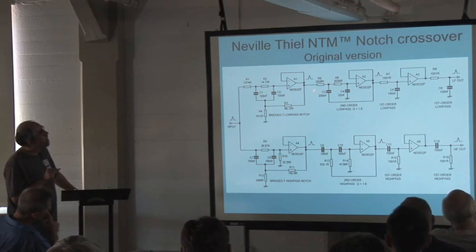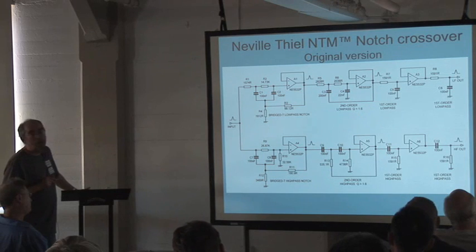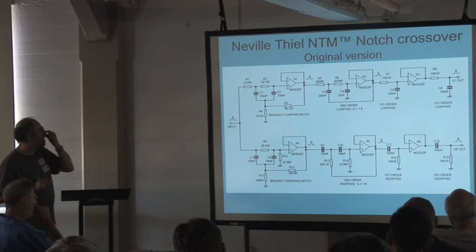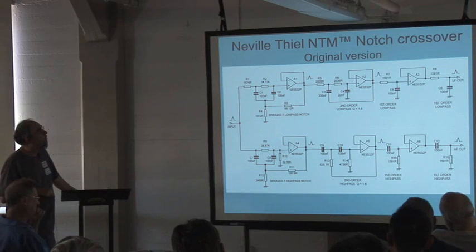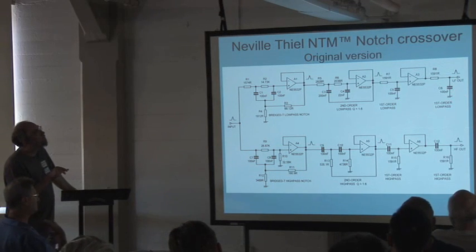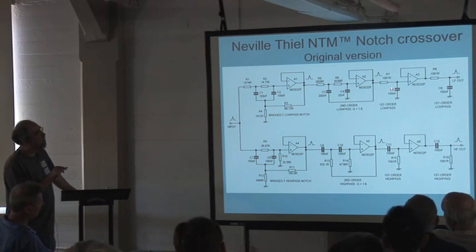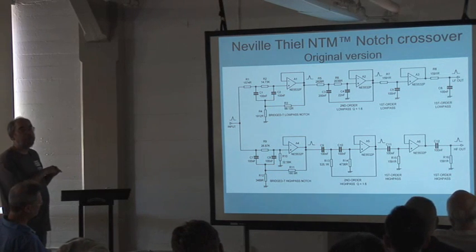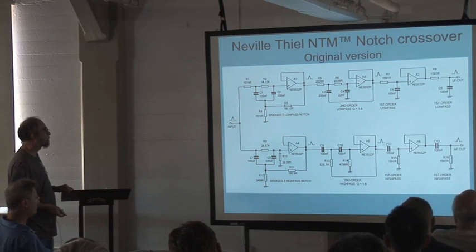Now you've got your peaking low pass filter. So the Q actually here is 1.6. Now that's quite high for a Sallen-Key filter, but it's not high enough to give you any really serious performance problems. You then have your first order low pass, and there's the second one. But of course you've got to put a buffer stage in between them, because otherwise this one will load that one, and you will not get the response you want. You won't get two separate minus 6 dB per octave roll-offs.